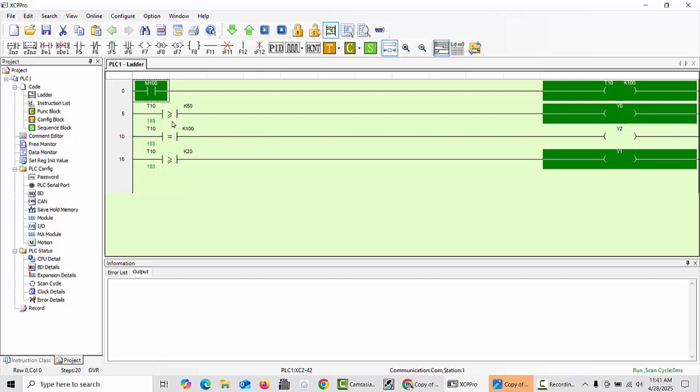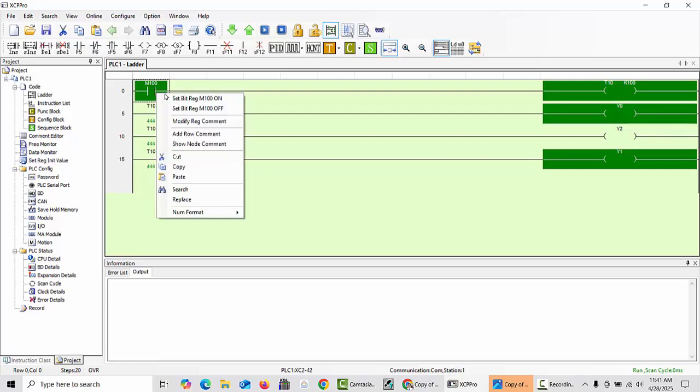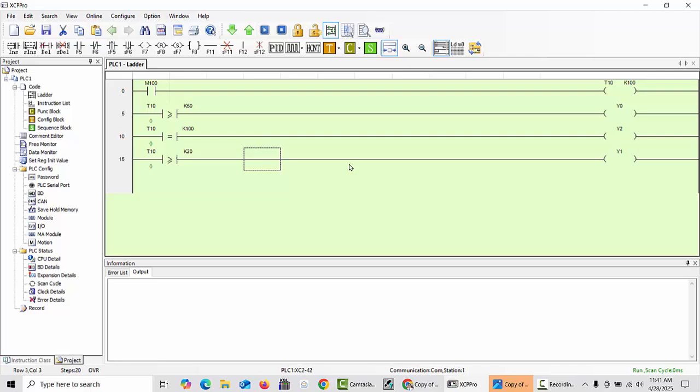And here we are using the greater than or equal command. This is up to 50 value, how much it goes, that's no issue, but our main point is the 50 value. When our timer reaches the 50 value, our output is on, and as it goes above 50, that's no issue, it will be continuously on. But this less than 20 is running. So with one more example we will understand how this command works.